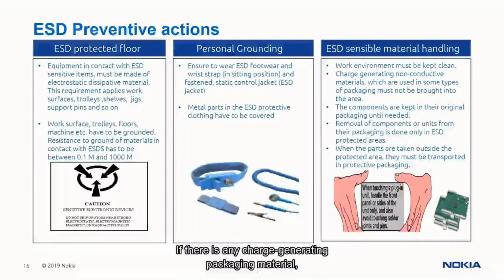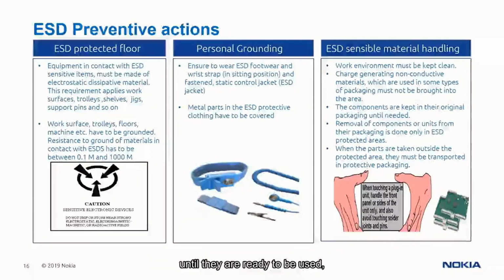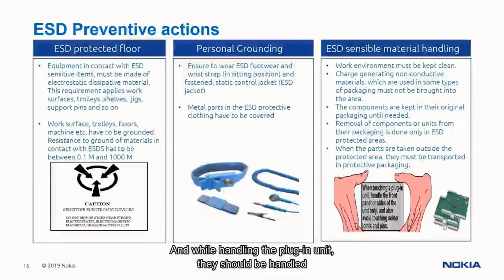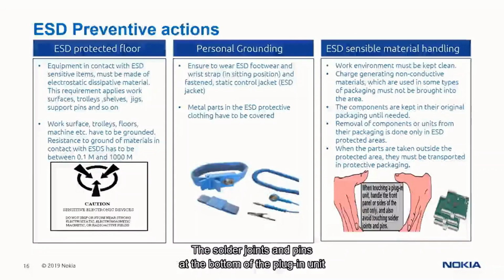If there is any charge-generating packaging material, it should never be kept in the work area. Components should not be taken out from the box until they are ready to be used, and when the parts are taken outside the protected area, they must be transported in protective packaging. And while handling the plug-in unit, they should be handled either from the front or from the side of the panel. The solder joints and pins at the bottom of the plug-in unit should never be touched. So these are some of the actions that we can take to avoid permanent damage to our plug-in units due to ESD.